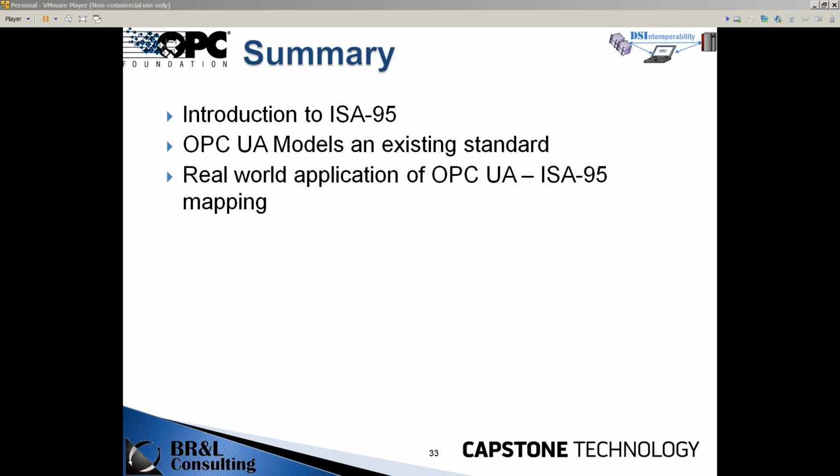Yeah, just a few points. As I mentioned before, the ISA95 standard is an implementation-independent, abstract model. It takes implementations of that. What we found when we were doing the B2MML was that it worked really well when we're talking to business level systems, when we're talking about transaction rates that can be measured in minutes or multiples of seconds, but it doesn't work real well at high speeds. What I view the OPC UA 95 companion spec as is a way to get the speed matching that we currently have.